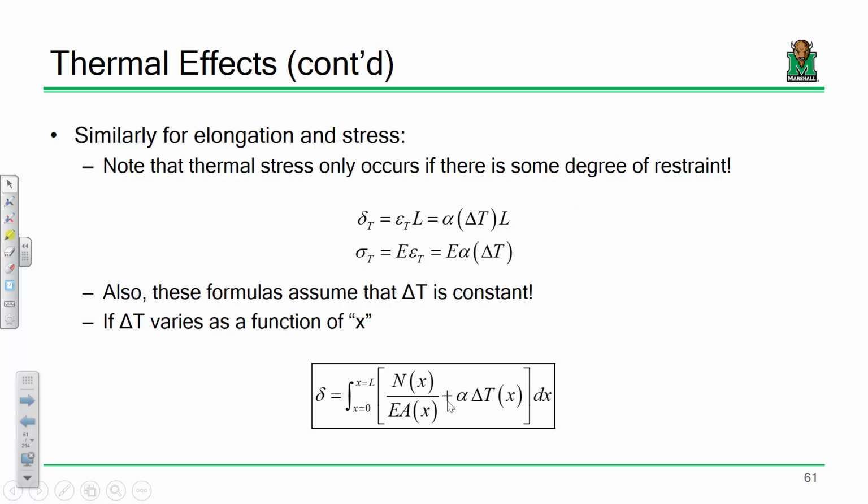And that's one of the big differences with thermal loading. I mean, the only way that you get mechanical deformation is if you take something and you put force on it. You yank it, or you compress it, or you bend it, or what have you. How you get mechanical deformation is by applying stress. But you can get thermal deformation by not applying any stress at all. You can heat it up, and that'll cause it to expand, but it won't stress it. The only time that you ever get thermal stress is if there's some degree of restraint.